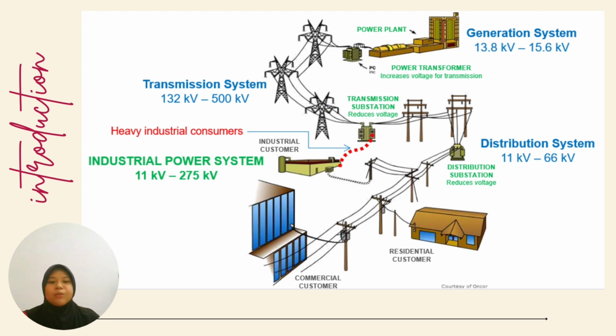In industrial power distribution, a step-down transformer is used to step down high voltage to low voltage, and a step-up transformer does the opposite operation of a step-down transformer. Efficiency and simplicity are the main factors in the design of distribution transformers. Distribution transformers are designed to run at maximum efficiency between 60 and 70% of load, which helps reduce the core loss.